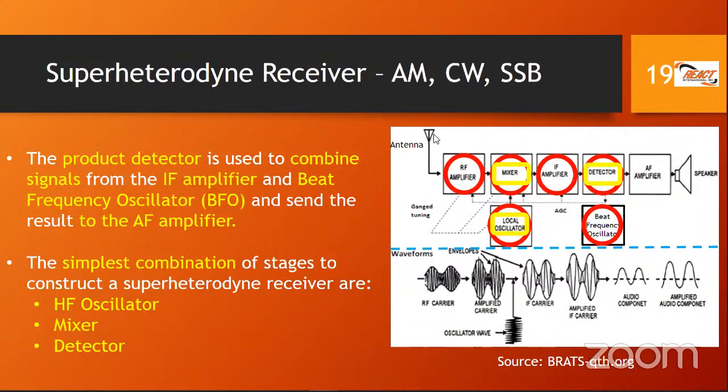So that is exactly how a receiver works. And if you think about it, you turn your radio on, your handy HF transceiver, and you're listening to your amateur radio colleague talking. It's coming through the RF stage. It's being mixed with the local oscillator. It goes to an IF frequency. That frequency then has a detector that mixes it with a BFO. And next thing you have your audio, and you're listening to the amateur radio operator.